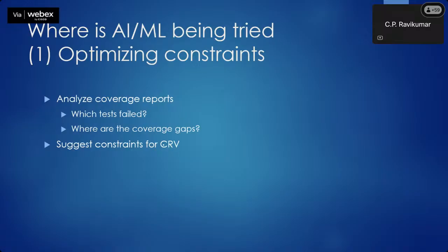These two are the only ones that get impacted. There is no relation between instruction and R1, R2, etc. So you may have to write more complex random constraints to handle all those complicated situations. Like if the opcode is jump, then choose these two registers. If it is add, then maybe certain modes are permitted, whereas if it is multiplication, some other.